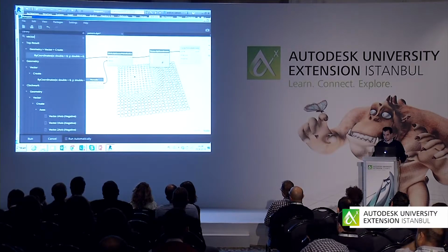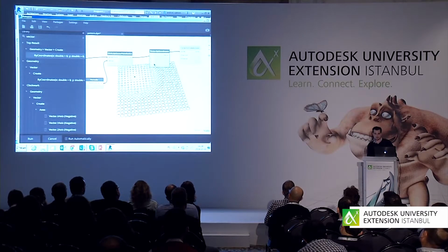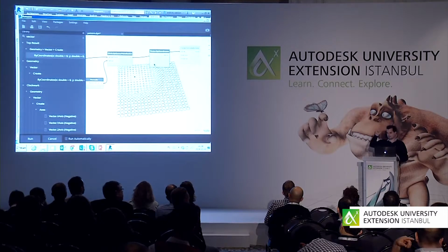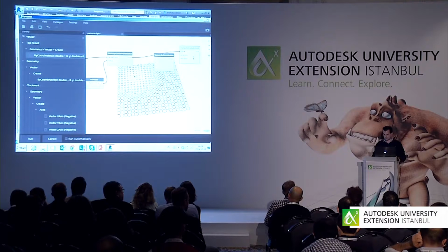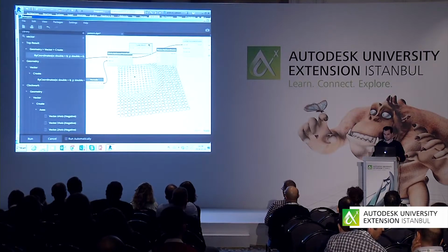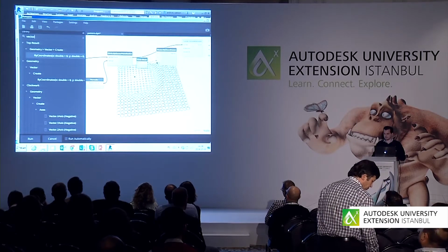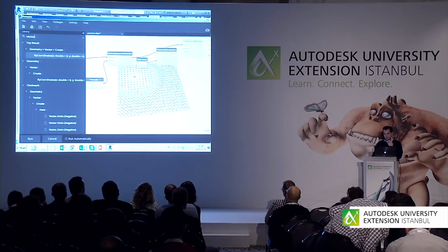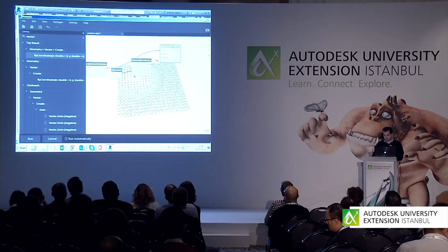For the moment, obviously, I want to extrude my circles along the Z. I wanted them to be straight, perfectly vertical. So if I double click on the canvas and type in 1, it's okay for Dynamo that my vector will be long 1. So this is direction.